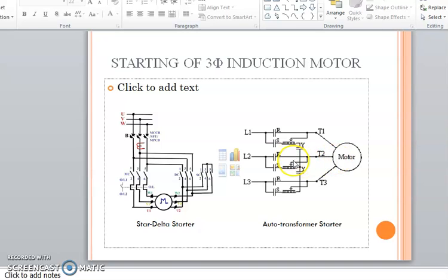We don't have any neutral line connected. So you just need your red, yellow, blue to be connected to your motor. Here is your source, directly connected to the motor. So in between your source and your motor, you just put whatever measurement apparatus or device that you need to gain the data from the exercise or your setting.